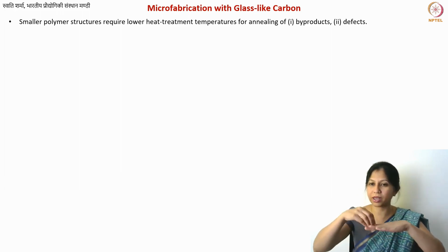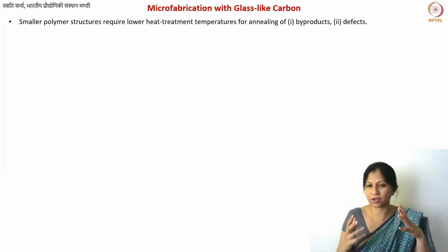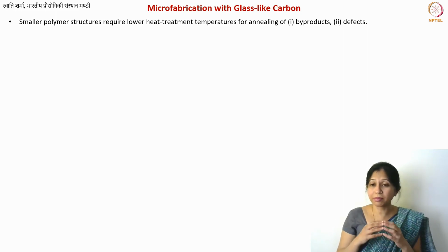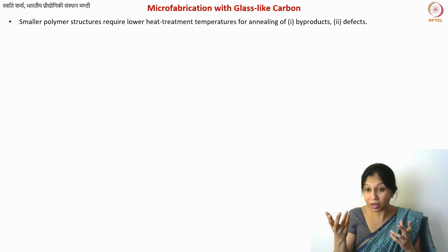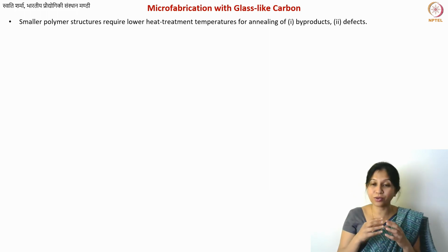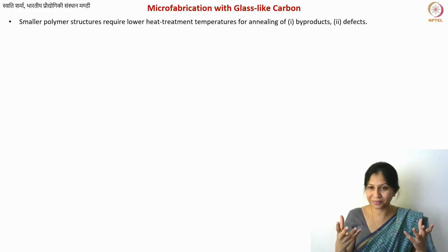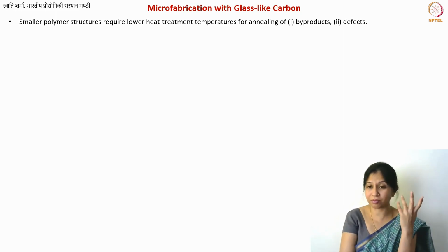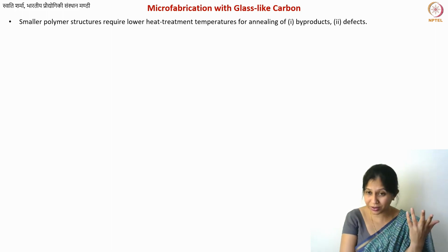On top of that you will make your devices or structures or whatever. Because micrometer scale things can be very small, you can imagine that. So these, you will not make them individually. You will rather do a batch fabrication process, which in fact is the advantage of microfabrication. So the fundamental idea of microfabrication, or reducing the size of the structures and devices, is, number one, to be able to use less material and do batch fabrication.